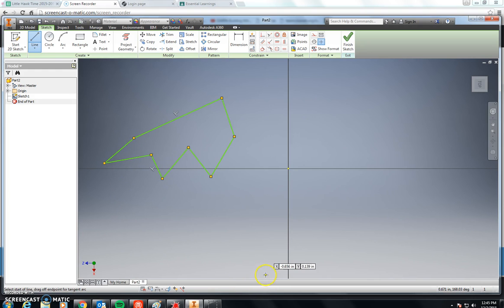Now that would be a finished shape. Let me show you though that this would not work because that little piece is going to be a problem. It does not see that as a shape, that's only a line. So to get rid of extra stuff, you can use your trim tool and cut it off. Trim tool will cut anything back to the next line, or in between two lines. It's a handy tool. That looks like a closed loop to me.